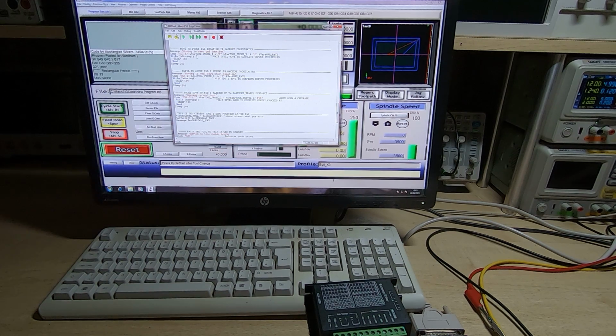It then moves to the X and Y location for our touch plate. So we'll look at the touch plate later, but you can look at it in terms of it being a probe. It's what the probe is going to see when the zeroing is carried out. Now we're using the tool itself as the probe, or at least the grounding for the probe. So the pad is really the probe just sitting there waiting for the tool to touch it, but it means that we can accurately locate the tip of the tool. So it moves above that pad.